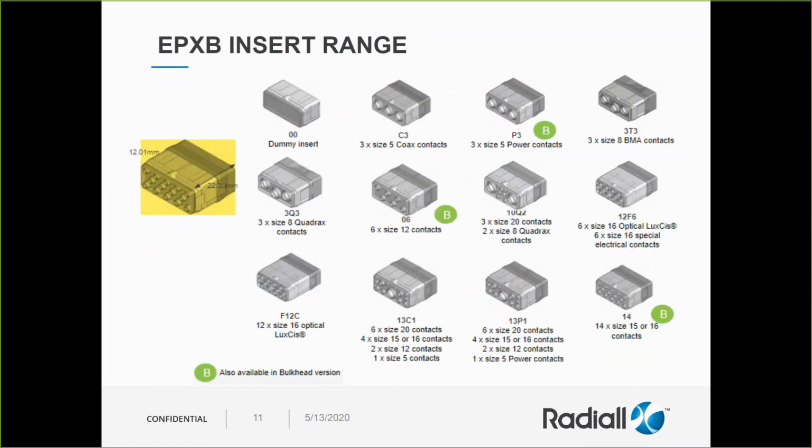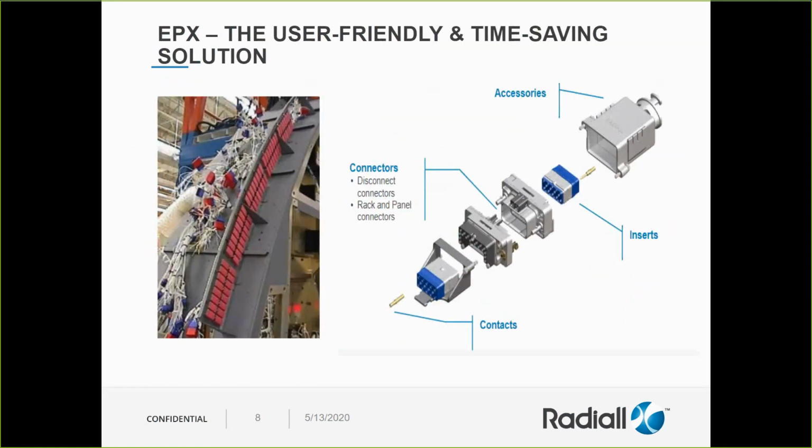Well, I can add to the fact that our connectors are metallized composites. So shell-to-shell conductivity happens through the metallized composite when they come together. There's also the grounding pins that allow them to be all grounded to one particular location. So in the picture that you see on the left, this is an application where all of the shells go off via the grounding blocks to a lug. So shell-to-shell connectivity happens via a grounding block, which you see in the part of the slide on the right.